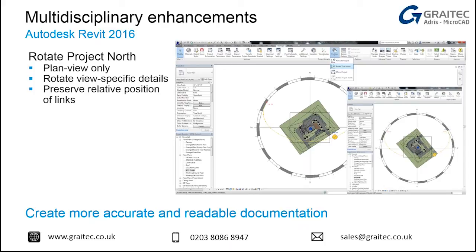If you ever rotated Project North before, annotation would start to go amiss. We've got improvements now to make sure that doesn't change. The idea of having a Project North and a True North is we can work perpendicular within Project North, but set True North so that our shadows are cast correctly. If we've placed our building where it's going to go, we can start to do solar studies and understand the impact of our shadows on other buildings and the impact of surrounding existing buildings on our development as well.